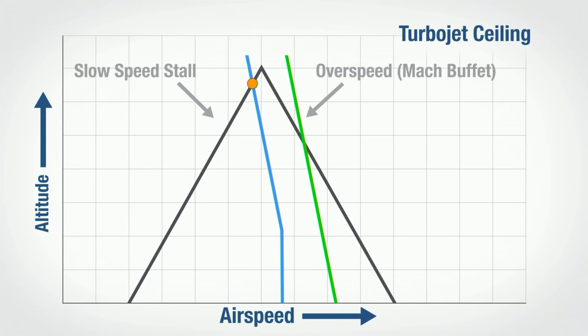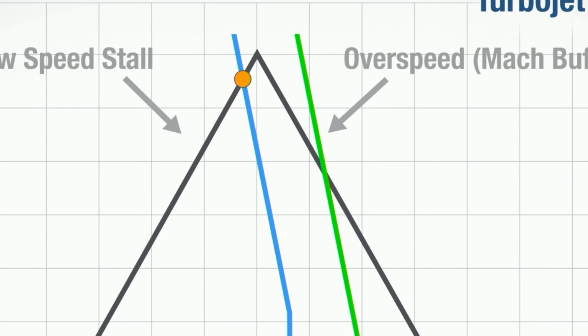One of the problems that we run up with thrust limited aircraft is they can end up essentially at a cruising speed that may not be very close to Mach buffet, but can be very, very close to their stalling speed. So if we go back to this chart, you could end up in a scenario possibly where the airplane was flying, let's say, maybe right here, okay? It wasn't using full power yet. It was flying right there.